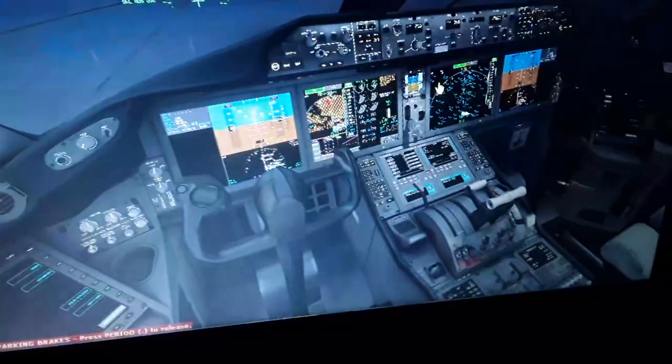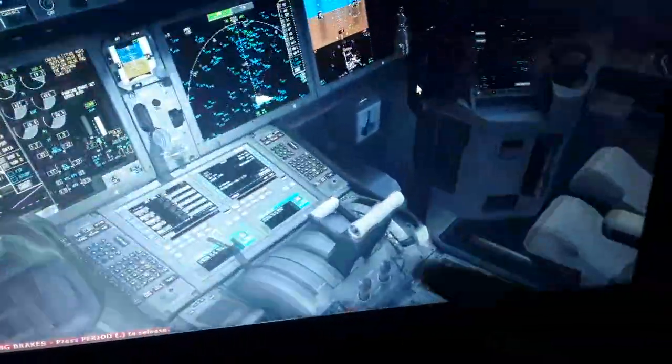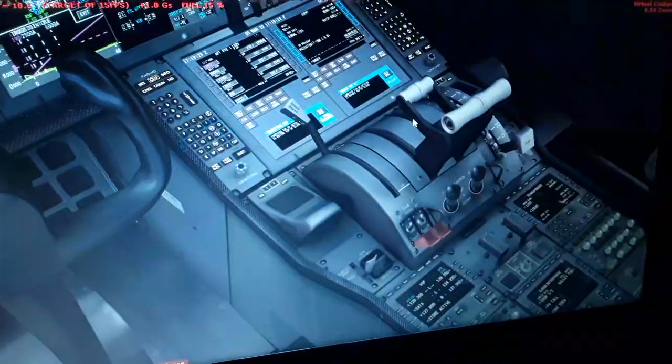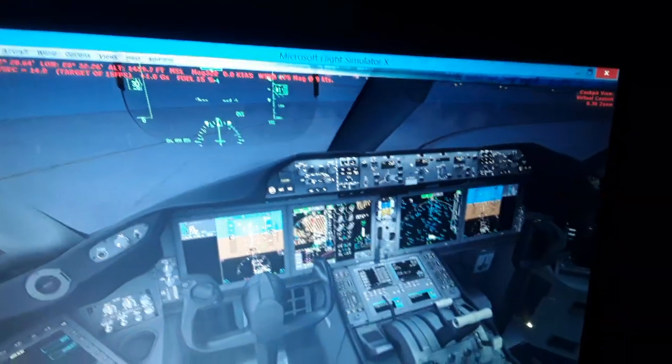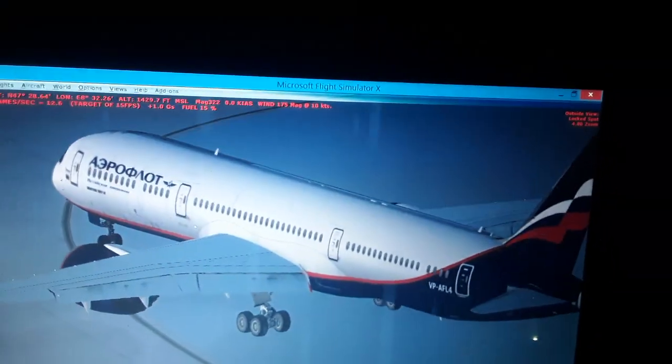This is also done vice versa as we descend from the cruise level to the elevation of the airport or sea level. So it's better than doing that manually like you do in the trainer aircraft. You have the automatic fuel mixture every second and pressure adjustment inside the engines and other adjustments.